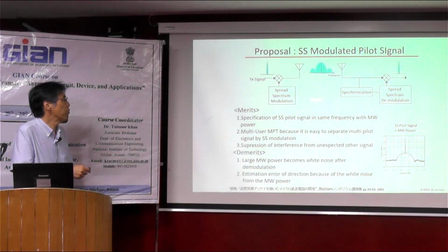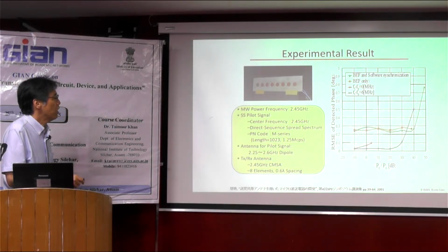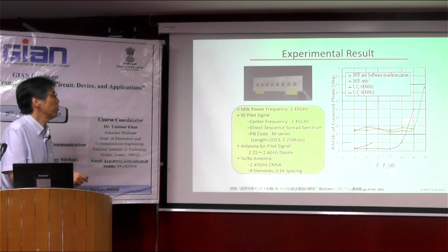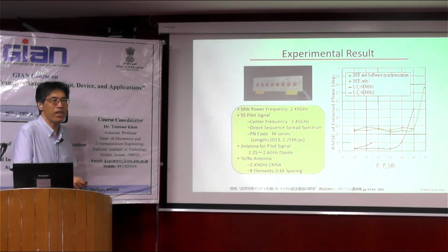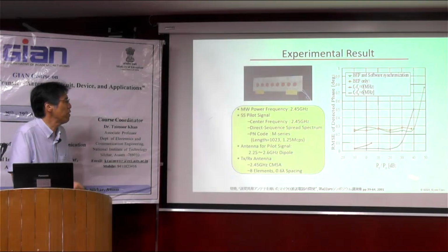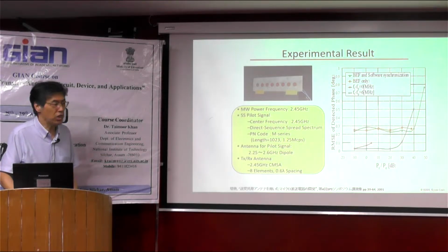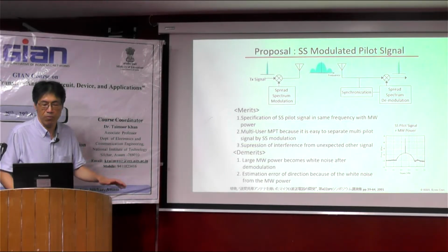So we proposed it and we carried out an experiment. When the power of the pilot signal is very weak, unfortunately, a phase error occurs. But we add a band elimination filter and suppress the microwave power into the pilot signal receiver, and we can reduce the phase error for this retrodirective system. So this is one interesting approach to suppress the interference between the same-frequency pilot signal and the high-power microwave beam.